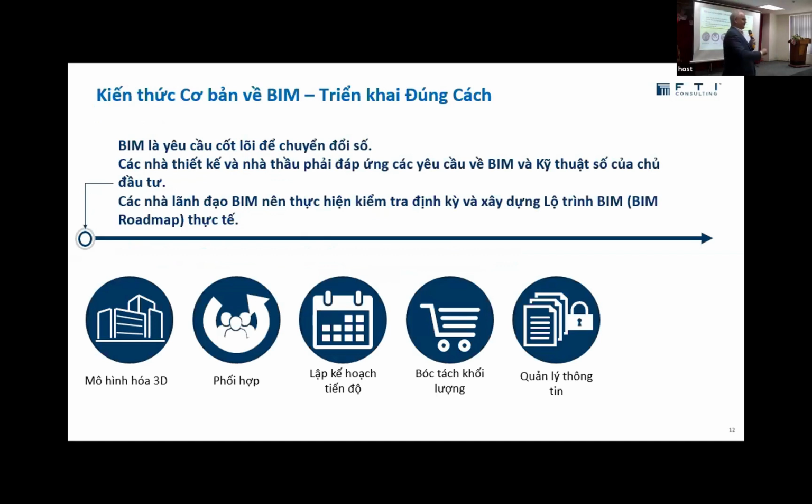Because if the drawings are coming first and the models are coming next, the quantities cannot be the same, the extraction cannot be the same, the schedules cannot be the same, and then you cannot rely on the models because what will happen, the architect will change the 2D drawing, they will issue the 2D drawing, and then the model is no longer correct. So if the drawings are the wrong way around, the model is less valuable. So when I say getting it right, I mean you start with the models. Then you do the coordination, then you can do your scheduling, etc.